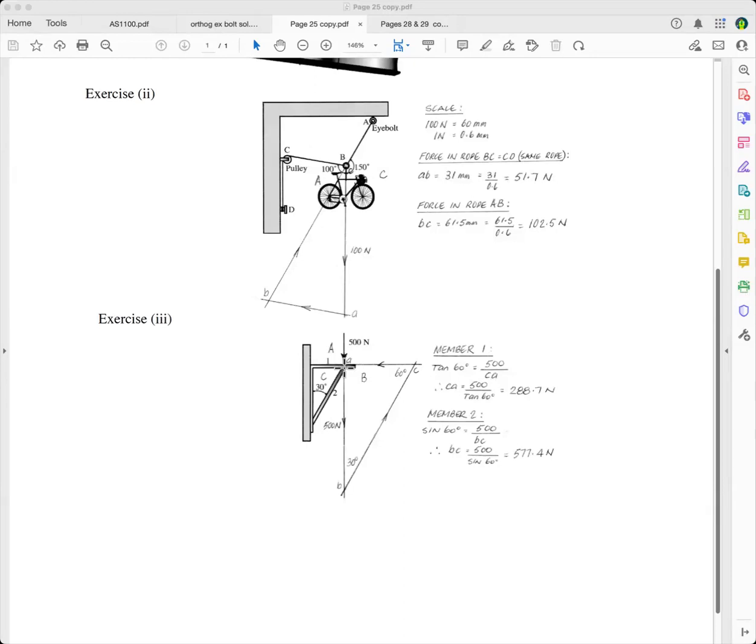You can't do it with 4 forces, because one of the forces will be indeterminate. And so, Bow's notation here: you know there's a force in there, and there's a force in there. And so we call that a force. So we've got A goes between there and there, B goes between there and there, and C goes between that force and that force there. And so you've got to start with the known force.